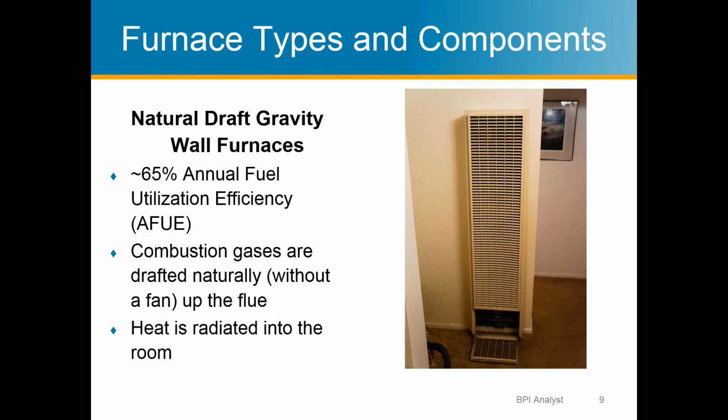Their AFUE, annual fuel utilization efficiency, is usually somewhere around 65%. When they're new, they don't get really much better than that. Most of the time they're naturally drafted, well, they're always naturally drafted, but there's usually no other mechanical or electrical systems inside. No fans or anything. This just operates off of the fact that heat rises,